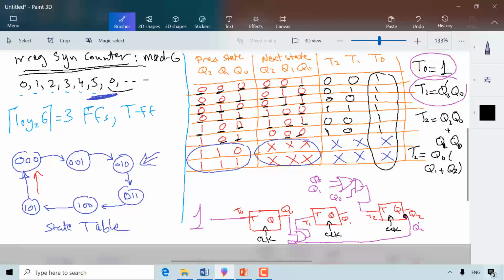All right, so this was example 1. Okay, let's move to the next 2 examples and we'll do them very quickly. We'll probably do it at the state machine level and then the continuation process. Now you are very familiar with the steps. First step is the state diagram, then the state table, minimization of the equations, and then finally the circuit.